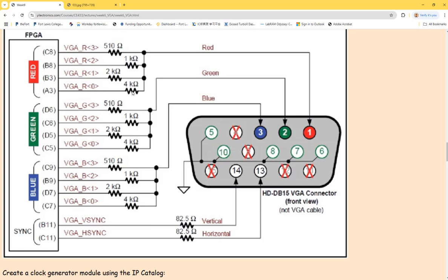You can see you have 4K and divided by 2, divided by 2, divided by 2. Okay? So in that case, if you apply superposition, could you let me know which one will give you a higher voltage? If you only apply that voltage pin to it, which one will contribute higher voltage to the V_L, the final output here?